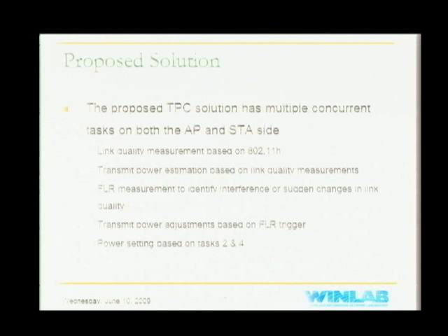No, but I didn't understand something. So what is it that you want? You want to make the transmission more reliable. So basically you want SNR to increase, right? So if you decrease both transmissions by 10 dB, the SNR doesn't change. So why do you say that you want to decrease the transmission power?